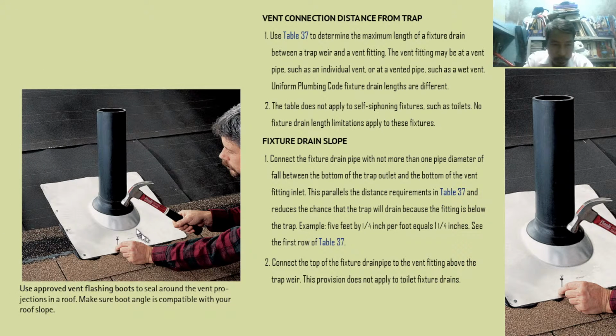So here, measure from the high side. This part is the high side. This part is the low side. Do not measure from this side going there. So measure from the high side. This is from the low side. Okay. So we need to measure it from the high side, from this point going up there. That is still more than 6 inches. That's why this installation is okay.